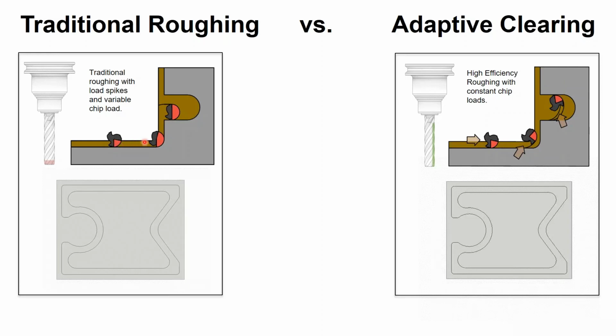When the tool comes into the corner here, we can see that a larger area of the milling tool is engaged in the material. That is when we can hear the machine screaming a little bit, or the tool could scream a little bit. Also, when we have a full wide cut like here, when we go into this pocket, most likely we have to reduce the feed rate for this section of the tool path, or we need to reduce the feed rate for the whole tool path to make it work. But the main thing is we only use the tip of the tool.